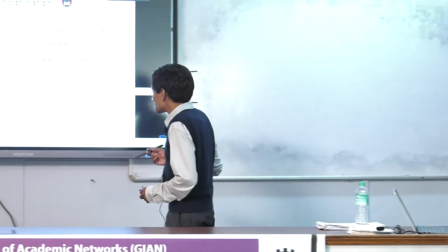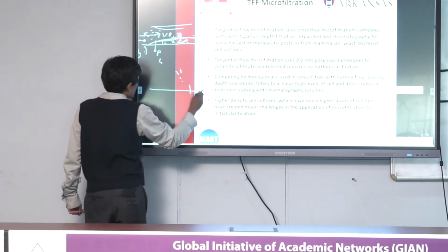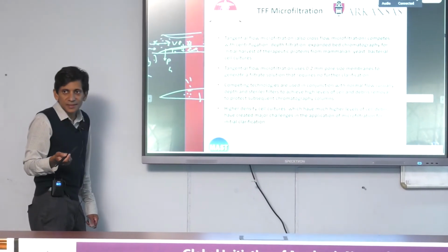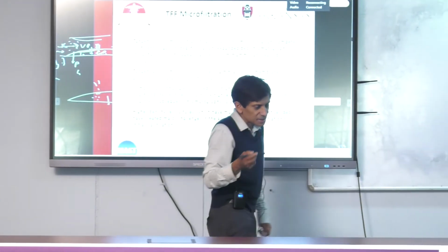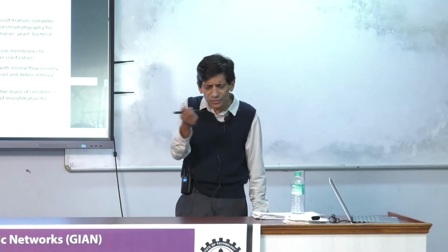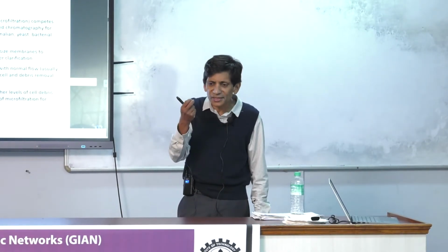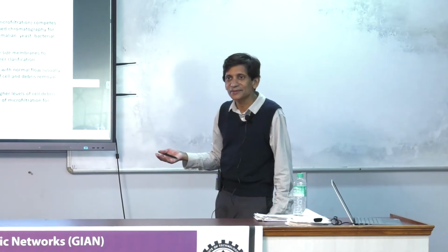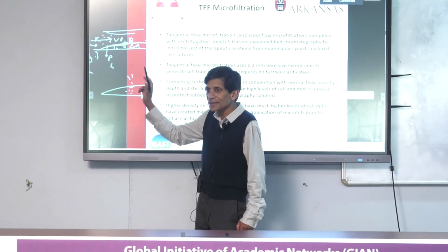And so the reason is this. This is for microfiltration. So for microfiltration, you're talking about particles, right? So let me draw this again now. So here's this. You're talking about particulate matter, micron-sized particles, say, that are moving there, okay? Now, the Brownian diffusion coefficient, if you may remember, goes inversely with the radius of the species. But for micron-sized particles, if you try to calculate, and you can do that, you'll find it's tiny, okay? Brownian diffusion works very well for proteins, for small species, for sodium chloride, things like this. For micron-sized particles, it's tiny, okay? So the problem is then the Brownian diffusion coefficient is not very well predicting the back migration.